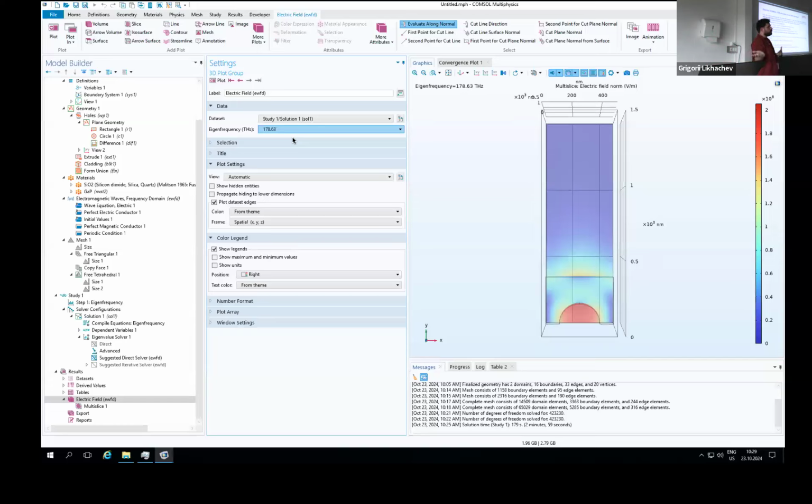So now we saw that with a pitch of 500, I think we used 550 maybe, 500, okay. We saw that the band gap was between 150 and 175, something like that. So it means that the center frequency is what, 163, something like that. So if you wanted to bring this band gap up to 193, it means that your pitch needs to be reduced. And that goes in the direction of those formulas that I showed you before about the lambda quarters. It means that the thicknesses that we picked were too large overall. So you'll have to reduce the pitch to bring the band gap up.